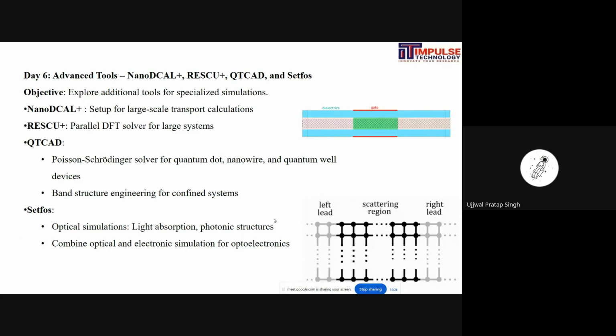NanoDcal Plus is set up for large-scale transport calculation, and Rescue Plus is a parallel DFT solver for large systems. QTCAD is a quantum technology computer-aided design tool where you can find properties like Coulomb blockade, charge potentials, Schrodinger and Poisson solvers, quantum dot, nanowire, and quantum well devices, and band structure engineering for confined systems. SETFOS is for optical simulation like light absorption and photonic structure, combining optical and electronic simulation for optoelectronics.